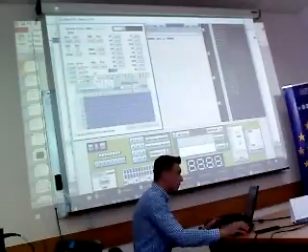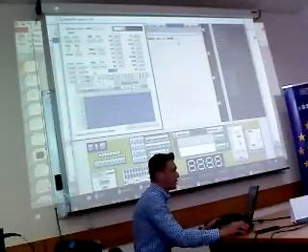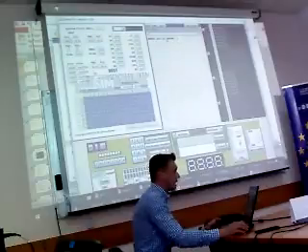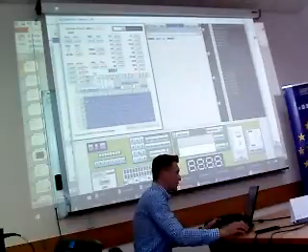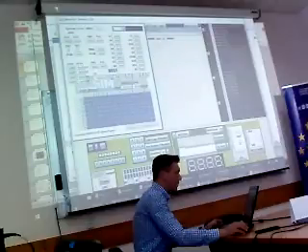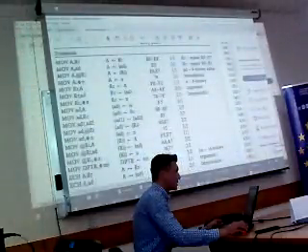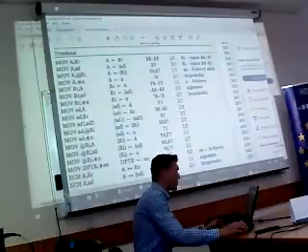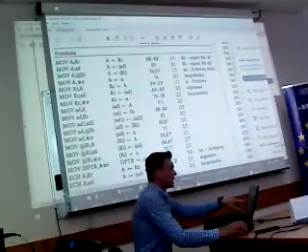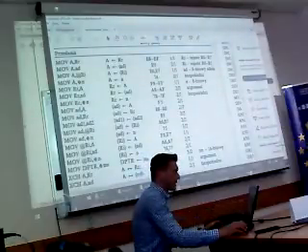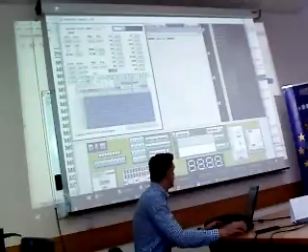So we can see the data memory and program memory or code memory. In code memory, we've got the code we've just written, and the code is about moving some data to accumulator, and we can see that we've got 2 bytes here in the memory. So we can compare it to the list of instructions, and in the list of instructions we can see that this instruction which we are talking about, code, is 74, and exactly the same code we can see here in our code memory.